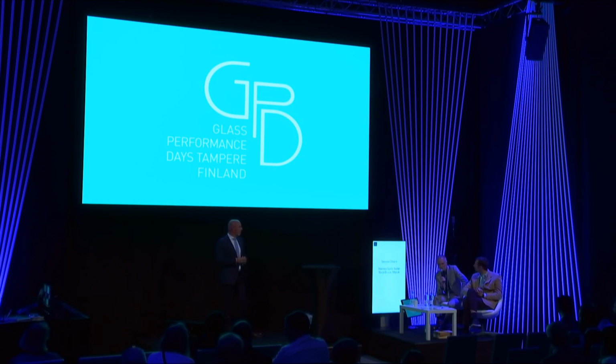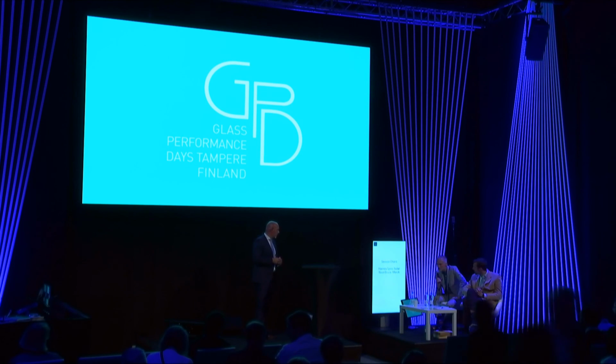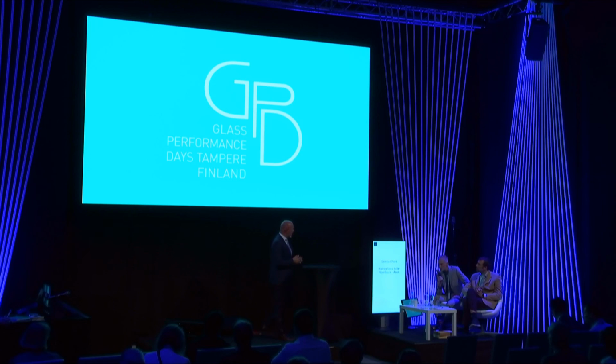I think we're just about done with questions. I have one relating to the shear strength of the product. Sometimes when you make a large unit, because of the self-weight of the glass, you get some shear forces into the spacer bar. Some spacer bars break, unfortunately. How is the TPS in terms of shear? How does it react when one glass slumps or tends to move?